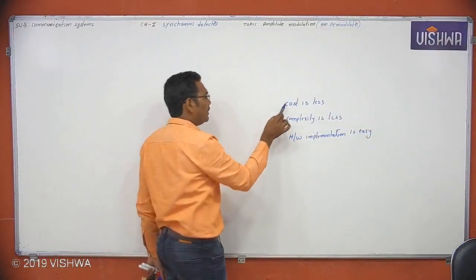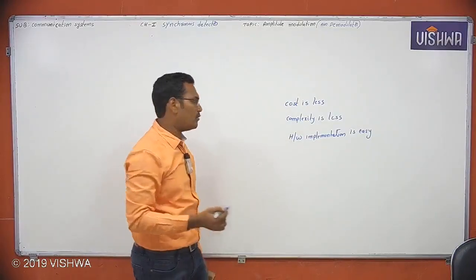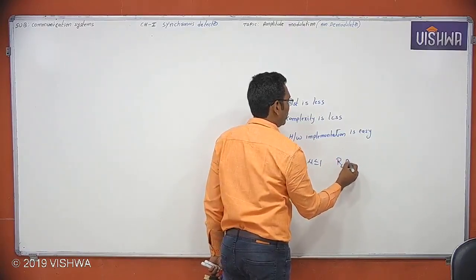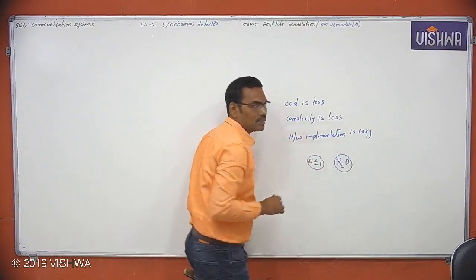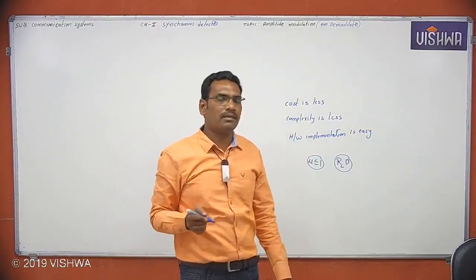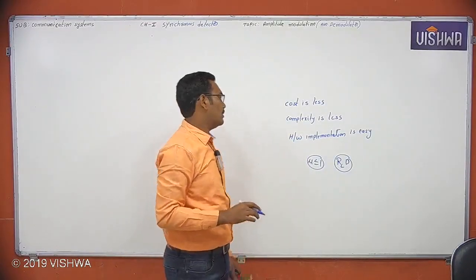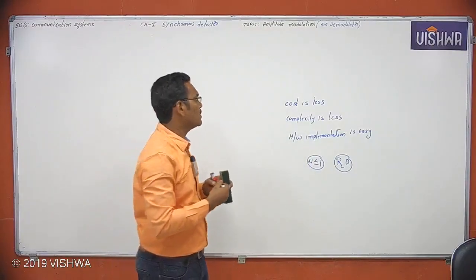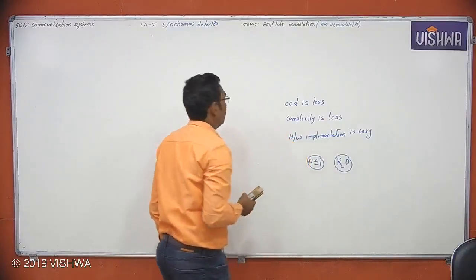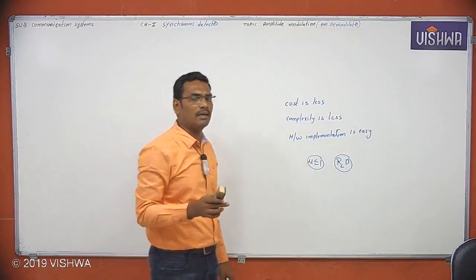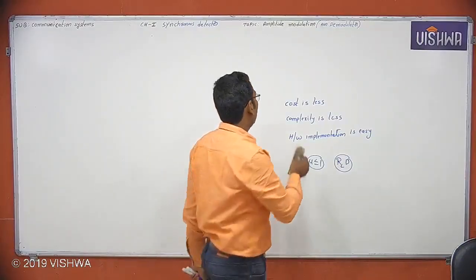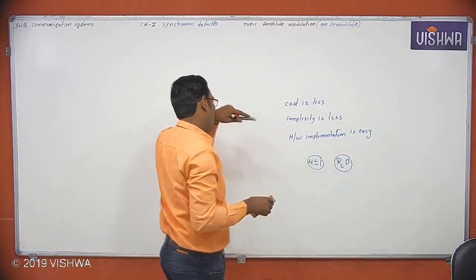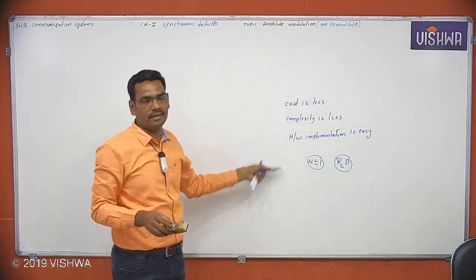Now, to gain these advantages, we have to choose the condition mu is less than or equal to 1, and a suitable time constant. Now all these conditions we are concentrating on, okay. But some of the students are asking, no sir, I am not interested in these conditions, this addition, subtraction, all these things. If you want the message without the DC signal, I want to get the original message signal. That demodulation is nothing but the synchronous detector. But is that easy or not, and are you gaining this kind of advantages or not, you will see.